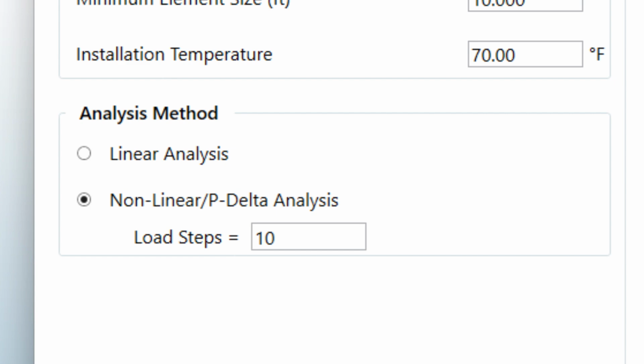Entering a larger number will result in a more accurate model, but it also takes significantly longer time to perform the analysis. A value of 10 represents good accuracy for almost all situations, and there are many cases where 3 might give good results. One strategy is to use 3 while you are building and debugging your model because the computation time is much faster. Then when you think you have your model refined, you can change it to 10 and see if the results are still acceptable.